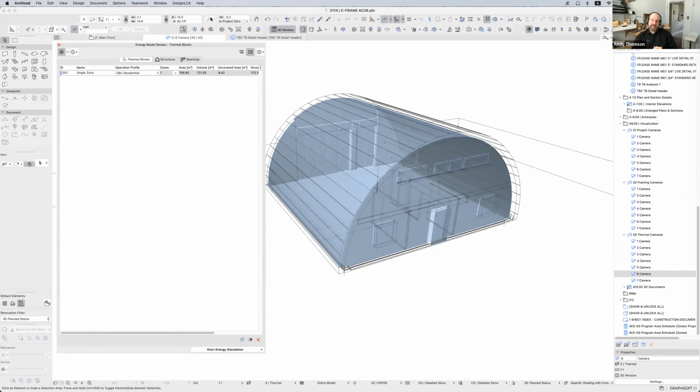They also considered that the activity level of the participants within the building was active or dancing, like partying, right? Whereas most of a wedding ceremony is sitting, milling around, having a drink, all that stuff happens later when the sun goes down. So when we started to break down what the engineer's model was assuming versus what our model was assuming, we started to find a way to communicate together to bring their loads down.